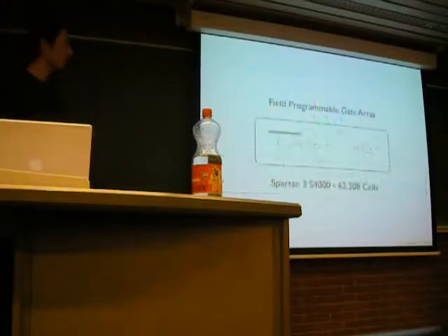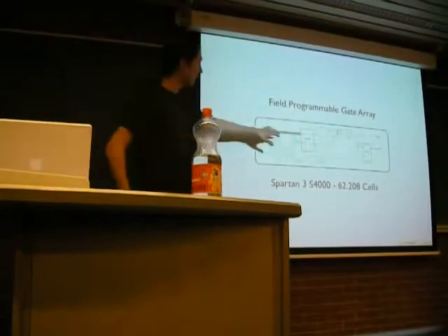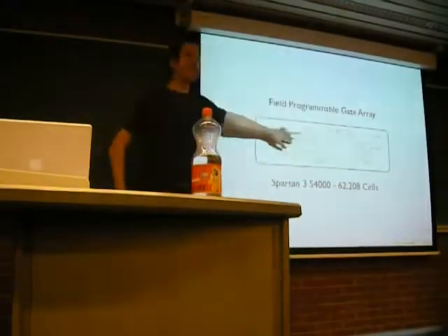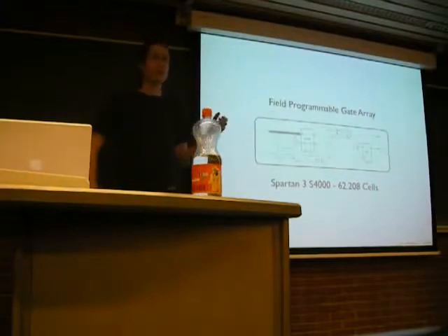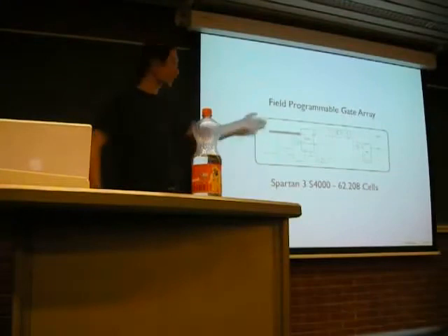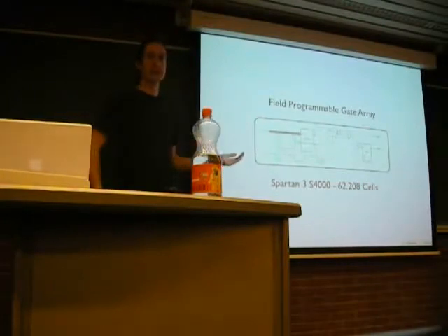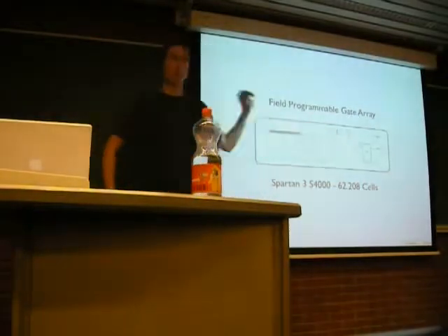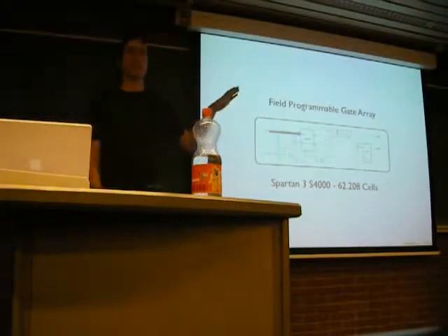But before we go through that one, I just want to discuss what a field programmable gate array is. First, I'm not entirely sure if everyone knows what it is. Really, an FPGA has 2 main components. The first part of this here, same part as that there, this is a lookup table. Really, it has 4 inputs and 1 output, and you can define for each combination of inputs what the output is supposed to be. So if all the inputs are 0, I want the output to be 1, and then if all but 1 input is 0, then I want the output to be something else, etc. And I can define those 16 combinations. The other part is a flip-flop, which can simply remember a bit. There's some other logic around it, but that's not really interesting at the moment.